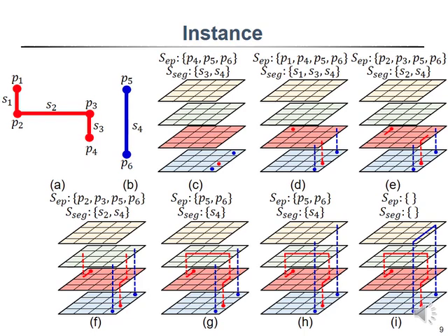Before tackling the wire segments on metal 2, we assign vias connecting metal 1 and metal 2 and deduct the demands in candidate endpoints from the tile capacity on metal 2. Note that in the rightmost column, due to the capacity deduction by vias, S4 cannot be directly assigned to metal 2.